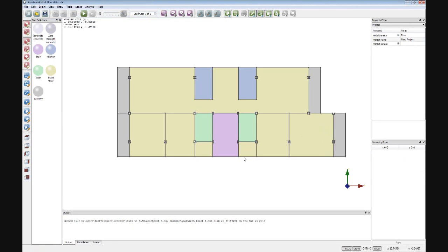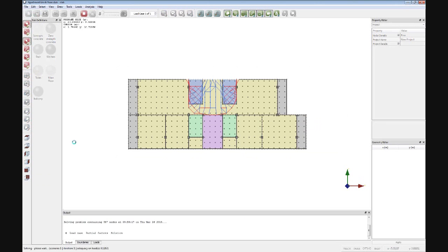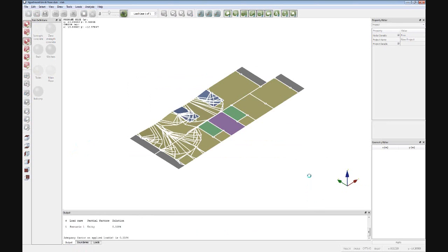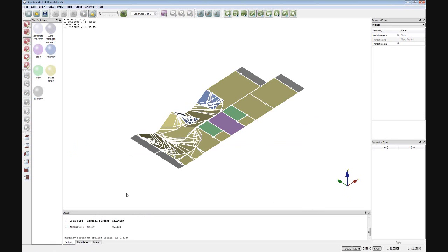as we've made it, and this is available within the example files of the software when you install it. So we've got all the different types of area where we're applying different materials and different loading to it, and you can solve it, and you can see that the software is very quickly homes in on the critical collapse mechanism for this particular problem.